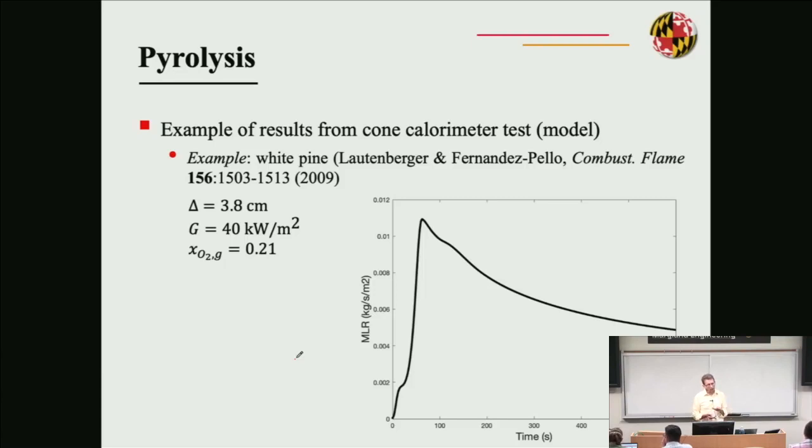So you have a piece of pine wood here that is 3.8 centimeter thick, 10 by 10 centimeter in a cone calorimeter experiment that is exposed to a radiant panel that is 40 kilowatt per meter square and in normal air. And you are looking at the thermal degradation of this piece of wood.